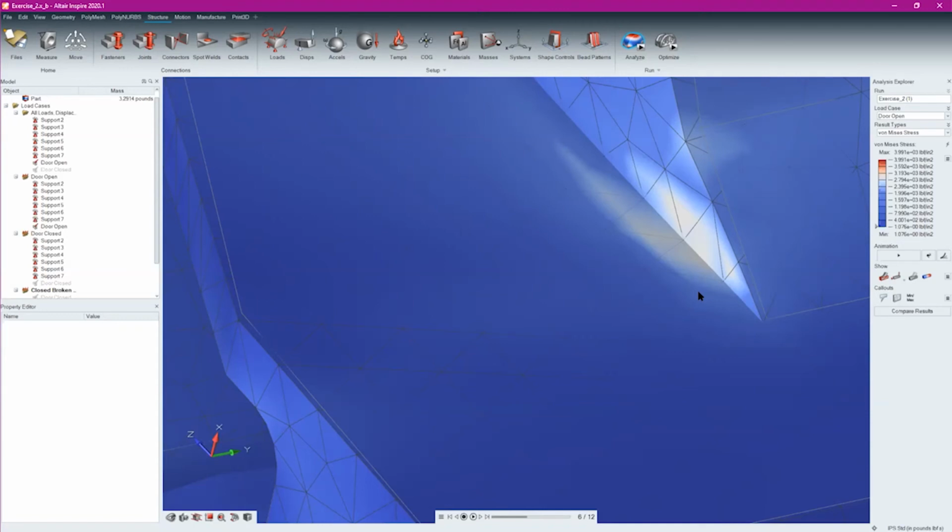So as long as your stresses are very, very localized, they typically don't see them as issues. And when you come to your final design, which will have fillets and everything on there, you'll probably get a much more realistic view of your actual stresses.